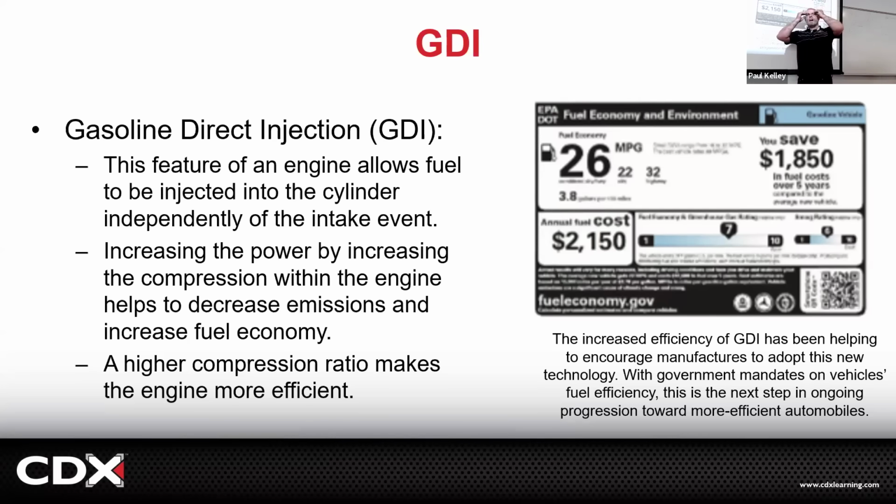So you're like, wait a minute. I got a 2008 Civic getting 28 miles per gallon, and I thought that was good. And I have a Camry, slightly larger car, and it's getting over 40. How did that happen? Well, I introduced to you gasoline direct injection. This is a big part of it right here. They do a little bit more than that. They're doing some stuff with the transmission, torque converter, lockup clutch. They're doing some stuff with Atkinson cycle on the actual engine itself. That's why the vacuum readings were weird on the video I demoed, because that's an Atkinson cycle.